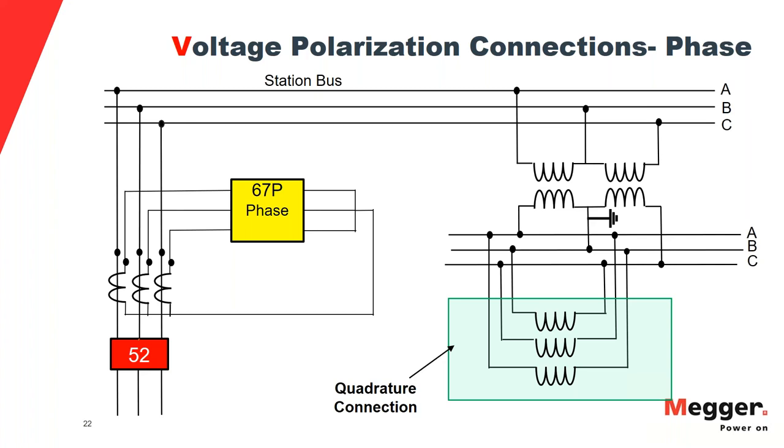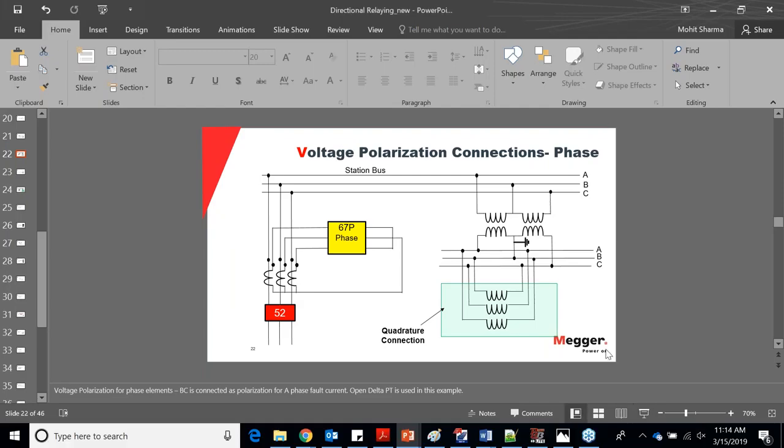Okay. Next question is for Mohit. If fault current always lags the fault voltage, please explain how the MTA could be advancing the polarizing voltage? As I explained earlier, fault current can lead the fault voltage as well.